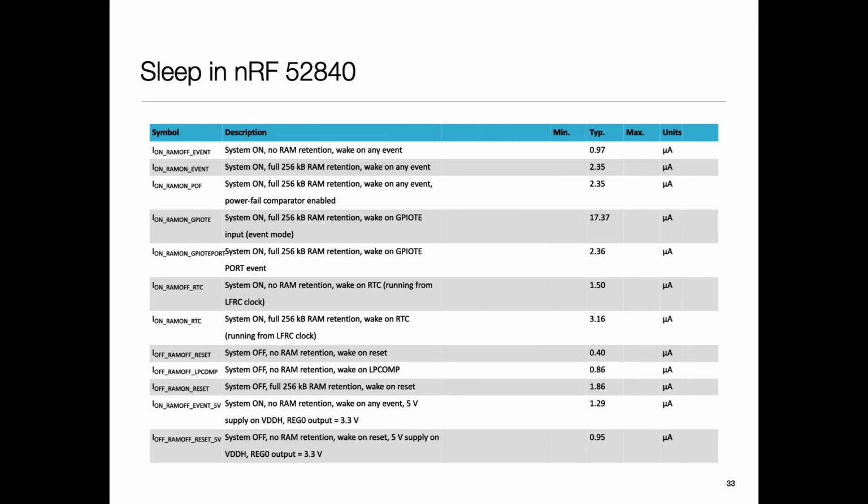Now think about the following. Let's say I gave you a choice of two sleep modes. Let's say a normal power consumption is 1 amp. I say, okay, you have one option of going to sleep. When you are in that mode, it costs 0.1 amp and it will take you 1 microsecond to get to it. There is another mode which will take you 10 microseconds to get to, but you would be at 0.01 microamp.